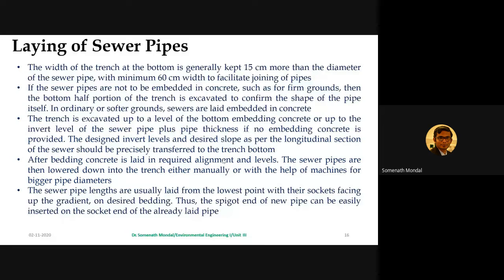So this is also another very important part. Both the things you need to keep in mind: diameter plus 15 and 60 centimeters. Whichever is more, you need to adopt that as far as trench width is concerned, with a minimum of 60. Now, if the sewer pipes are not to be embedded in the concrete, fine, and such as